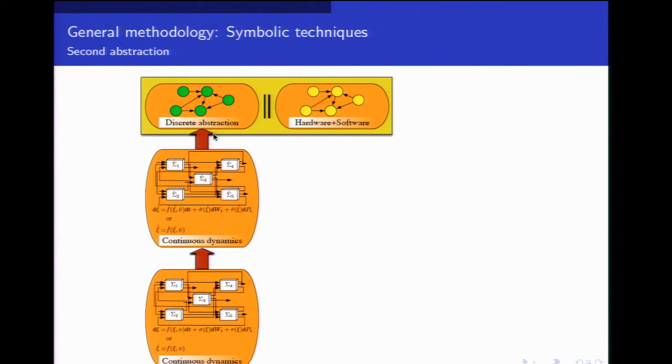You have a physical part, you have a cyber part, so now you have an overall modeling framework, all in the discrete domain, yeah? So now in the second phase, or actually the third phase, we synthesize a discrete controller for this overall dynamic, such that when I compose the discrete controller with the model in the discrete domain, the closed loop will satisfy those complex properties.